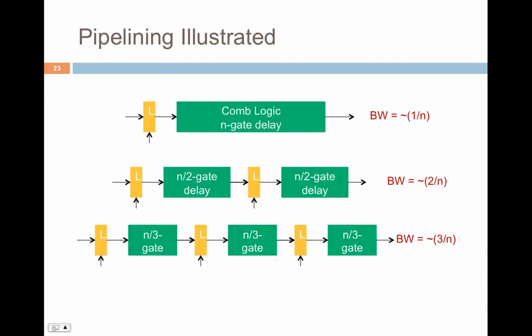And this was one of the basic premises of going for a higher number of pipeline stages. For example, when the Pentium 4 came, they were looking at 10, 15 stages. They were targeting even 20 stages, so that more stages would imply higher throughput. And of course, at one point in time, the latches would start playing a role. But the goal was that you wanted higher throughput, and more stages generally allowed you to do so.